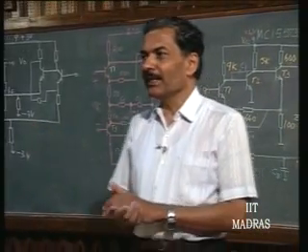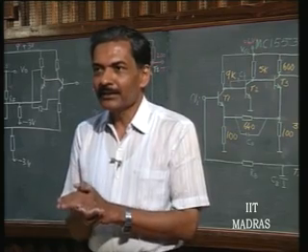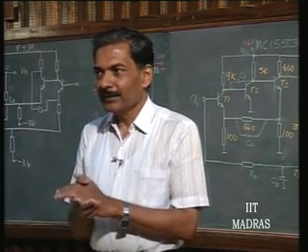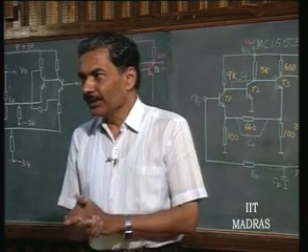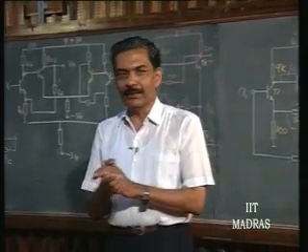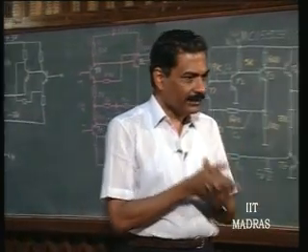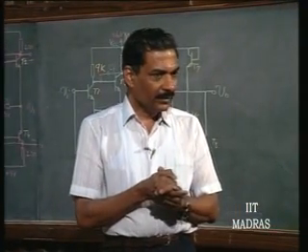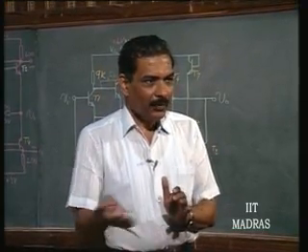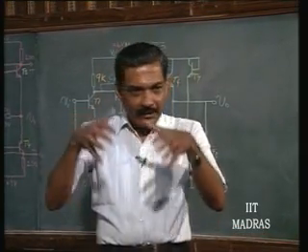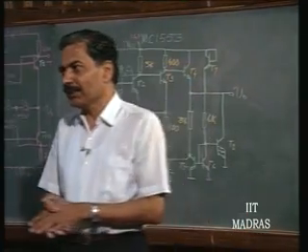That also is visible very clearly. It is the resistance that is directly across CF, that is RF, RF parallel CF. Okay. So, you can locate the 0 at RF parallel CF, okay, 1 over RF parallel CF. RF parallel CF is the time constant, okay, and cancel out one of the 3 poles.